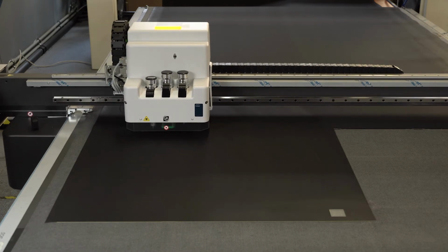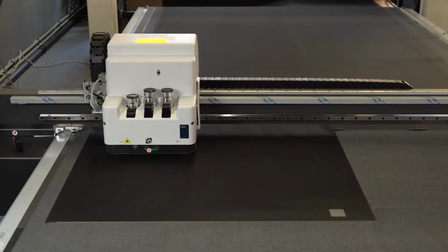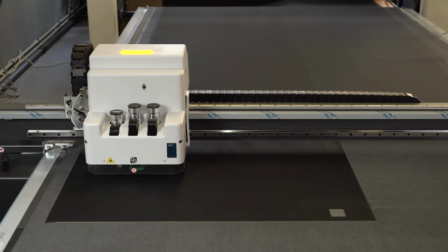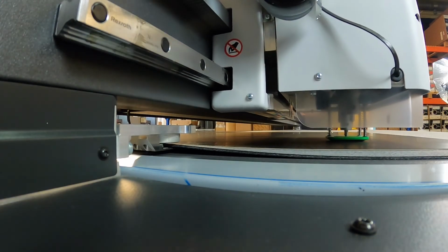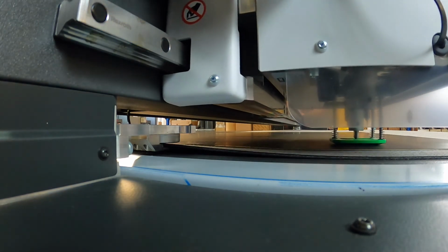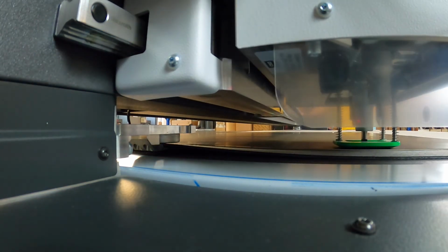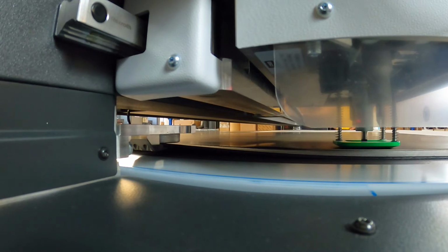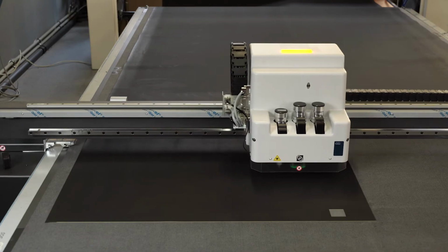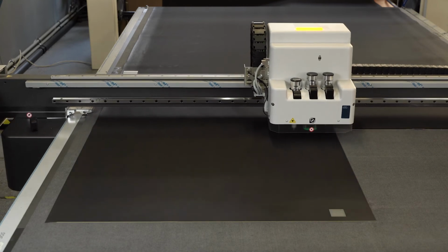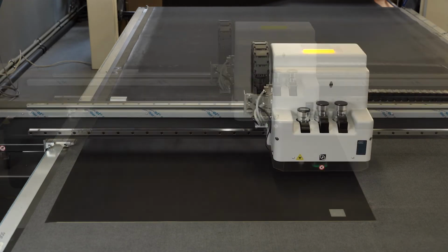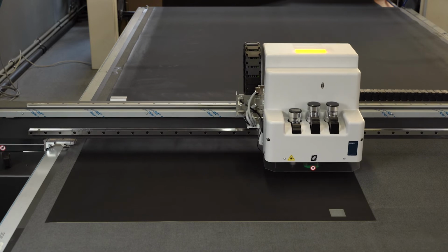Dynacoat is the ideal plate for selective lacquering. Its construction facilitates the perfect cutting of graphic elements. The applied blends of the rubber layer are adequate for varnishing with UV and dispersion varnishes. The fine sanding of the outer layer optimizes the transfer of the varnish. The design of the blanket achieves a balance between the essential ease of applying the freeform selection and resistance to delamination during use.